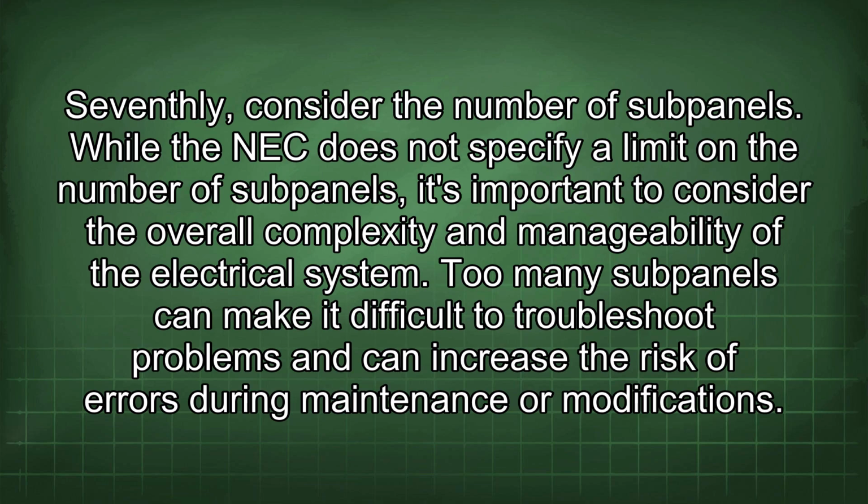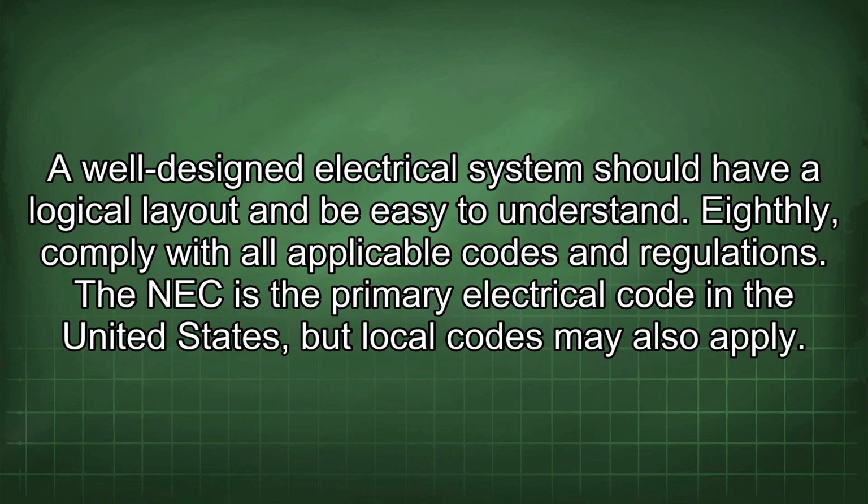Seventhly, consider the number of subpanels. While the NEC does not specify a limit on the number of subpanels, it's important to consider the overall complexity and manageability of the electrical system. Too many subpanels can make it difficult to troubleshoot problems and can increase the risk of errors during maintenance or modifications. A well-designed electrical system should have a logical layout and be easy to understand.